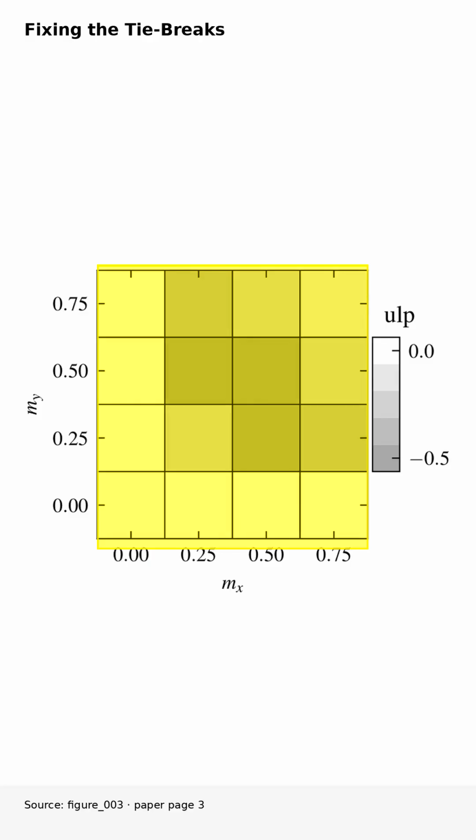While direct integer addition works perfectly for simpler rounding modes, standard round to nearest even, or RNE, requires a slight intervention. This new heat map plots the E5M2 multiplication error when comparing our logarithmic approximation directly against exact RNE rounding. The error landscape here is distinctly different from the baseline. The scale on the right reveals a purely discrete set of outcomes. The error is strictly either 0 in the white squares or exactly negative 1 ULP in the darker gray squares.